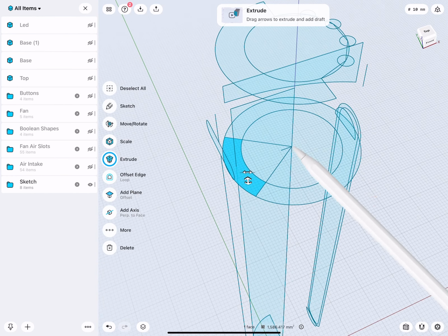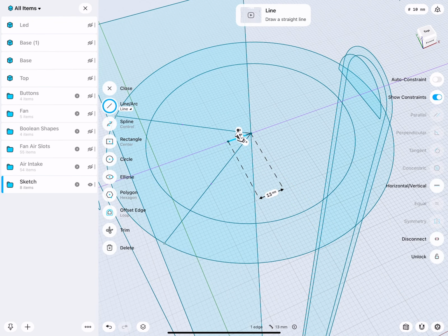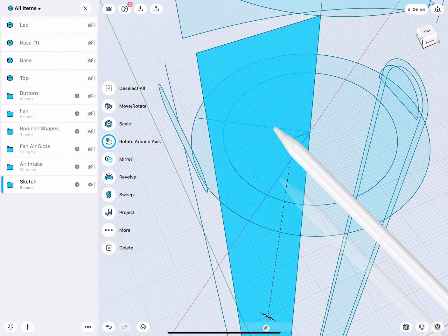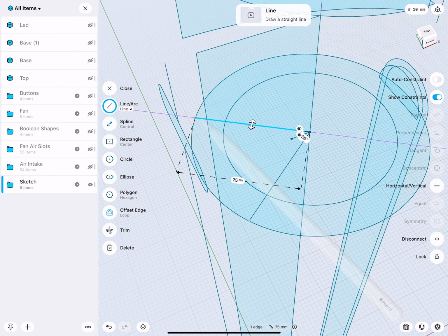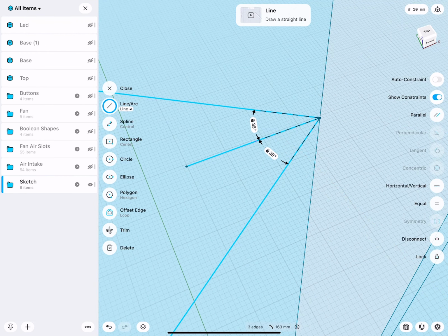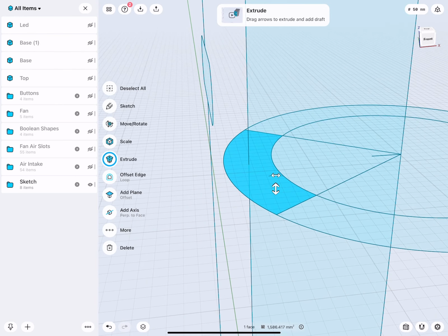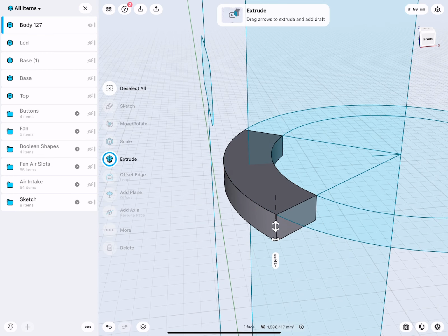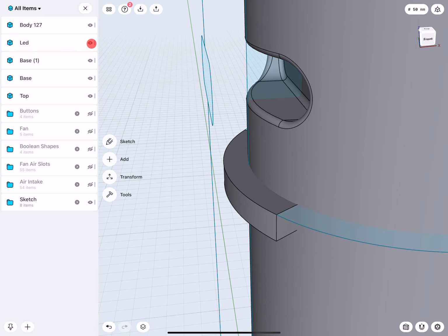So it's from the center of the cylinder that I drew these 2 lines. There and there. Including a horizontal line. And then with the dimensions, I was able to make these 2 lines have the same orientation, left and right. And then here I have a nice slice. So this slice, I will move down 10 millimeters. And let's take a look at the rest.